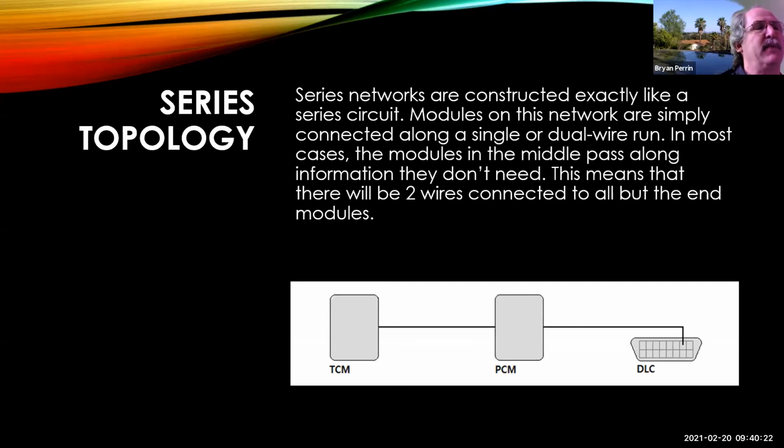And that's the best way to find resistance, because we flow so little current through here, your ohm meter is not going to pick up something that's going to cause a problem. Your ohm meter doesn't push enough. Yeah, if it's open, it's going to find it, but what if it's just got high resistance interfering with the signal? Yeah, I've got some noise on my scope, but is it noise that the computer's going to recognize? Plus the other advantage is I don't need to unplug anything to use a scope, where if I'm using an ohm meter, I've got to unplug both ends and do all that.